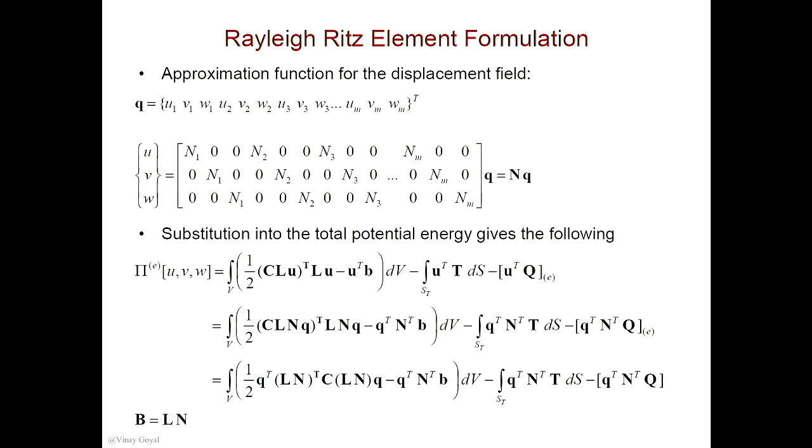So can I have the shape function the same for u and v? Let's say u is in the axial direction and v is transverse. The shape function will always be different like that? The actual shape functions for u, v, and w at each node will be the same. There's no reason not to make them the same.